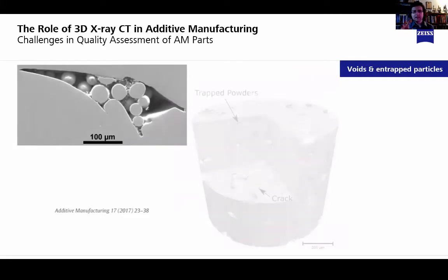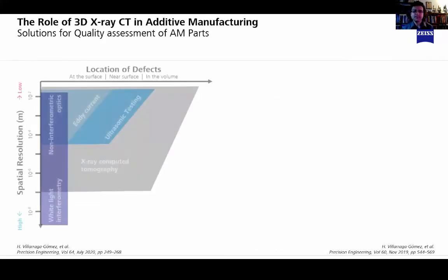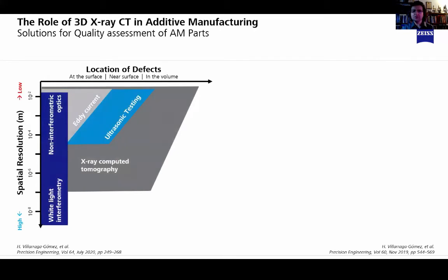And fourth, it is not surprising that additive manufactured parts might have unmelted powder particles on the inside, or some level of porosity that is difficult to assess without cutting or slicing the final product, unless you use X-ray technologies. There are actually several solutions for non-destructive inspection of additive manufactured parts.